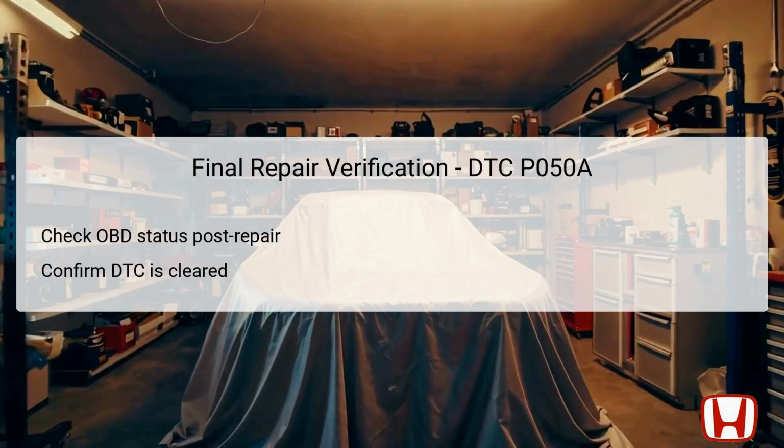Once all necessary repairs have been executed based on the previous diagnostics, it's important to verify that the vehicle is operating correctly. This can be done by checking the OBD status after repairs have been made. Use the HDS to confirm whether DTC P050A is cleared successfully and that there are no new codes present. Additionally, observe the engine's performance under cold start conditions to ensure the idle air control system functions appropriately.